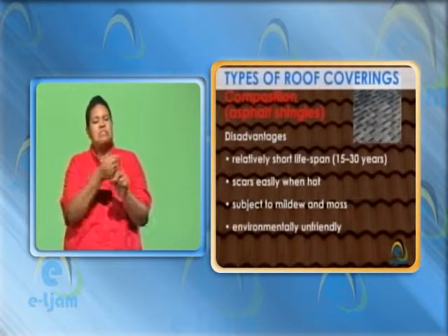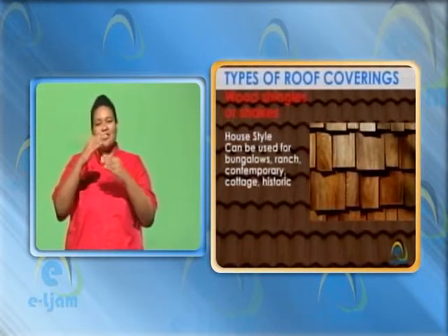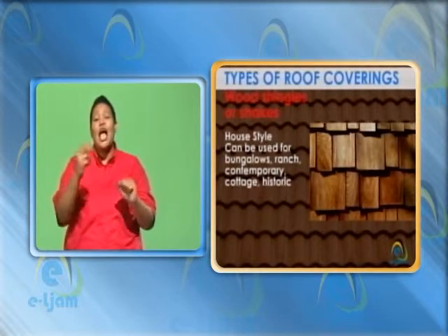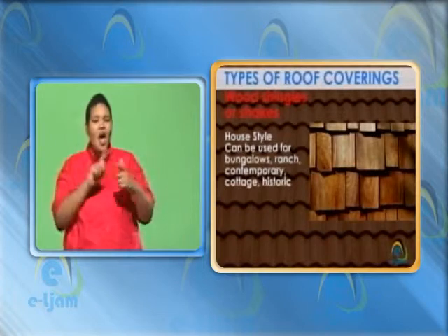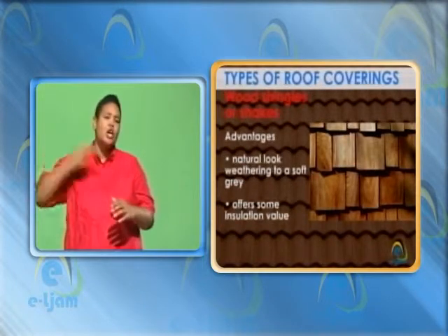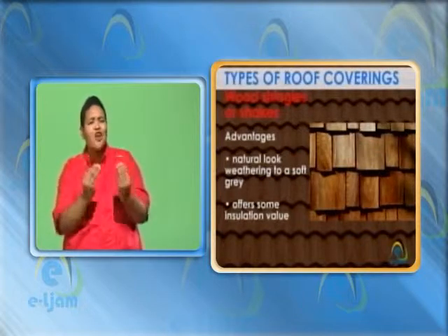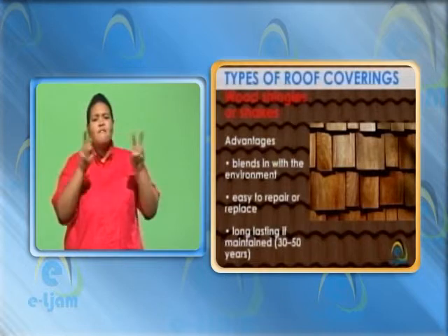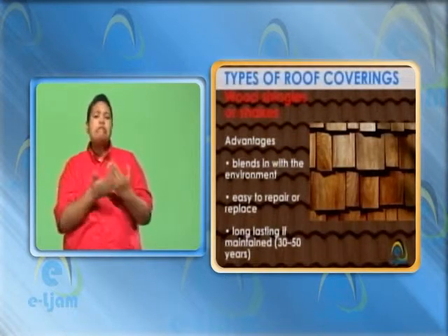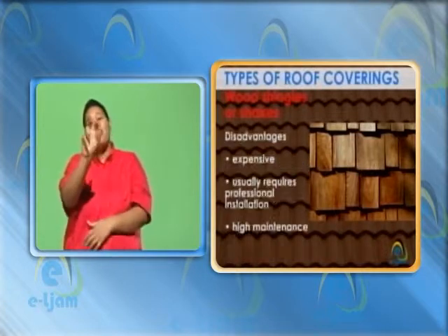Environmentally unfriendly. Wood shingles or shakes. House style: can be used for bungalows, ranch, contemporary, cottage, or historic. Advantages: natural look weathering to a soft gray. Offers some insulation value. Blends in with the environment. Easy to repair or replace. Long-lasting if maintained, 30 to 50 years.